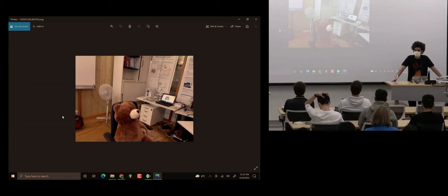Consequently, that causes difficulty for registering this image with the next one to find out the camera pose. We do have cameras with global shutter, and obviously that's preferred because they capture the entire image at one instant, and you don't see motion blur as much as you see here.